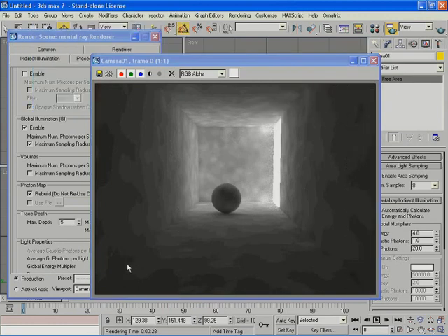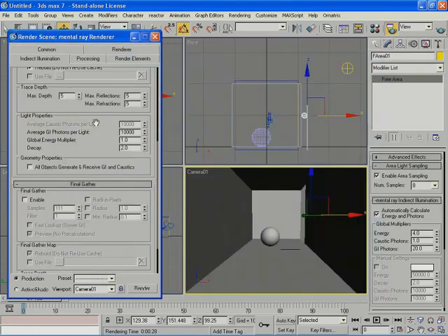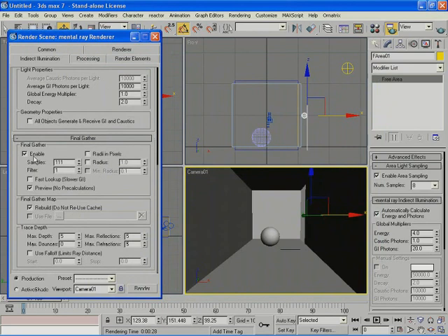I'm going to check preview, and here I have a fast lookup option. If I check it, first of all, I have the global illumination phase to calculate. Then I would have another phase, which is the fast lookup phase, and at the end I would have the final gathering phase. So I would have 3 phases to calculate. But if I uncheck fast lookup and I don't activate it, I would have only 2 phases, but the overall rendering will take more than if I did have fast lookup on. So on the final render, I have to check fast lookup because it will speed up the overall rendering. For now, I'm going to uncheck it because I'm still testing.